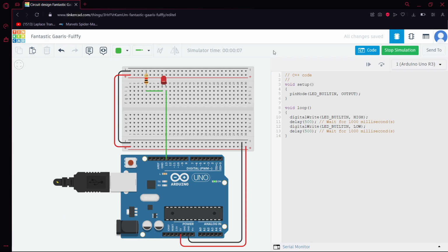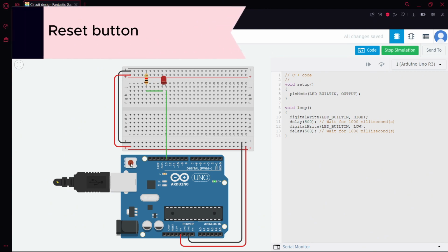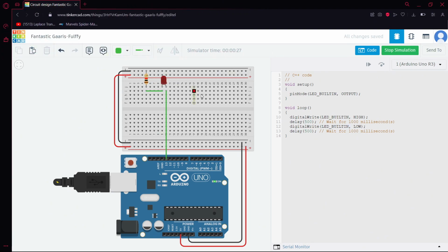We also have the reset button in the Arduino. The big red button in the hardware is the reset button wherein we can reset all process that is happening in our code and start it from the beginning. So in this small project, we can see that the program is already running by just using the Arduino R3 itself. But we can explore more and extend the circuit by connecting external LED to pin 13. This pin serves as our output pin that has LED and resistor built in already.